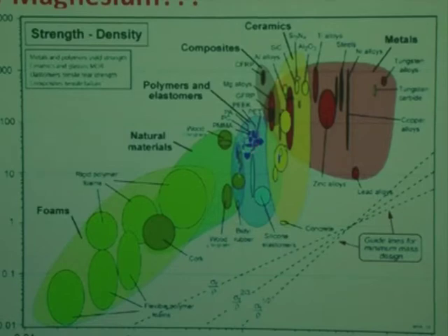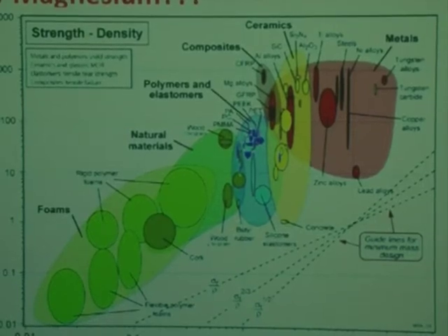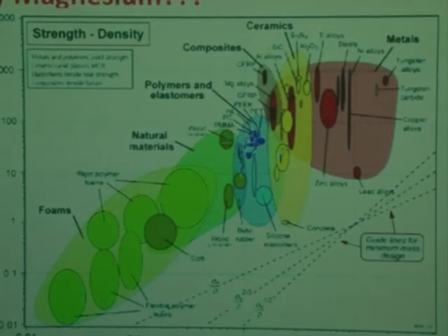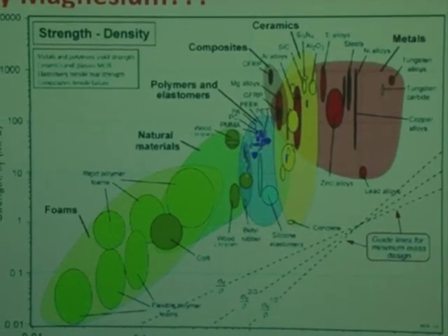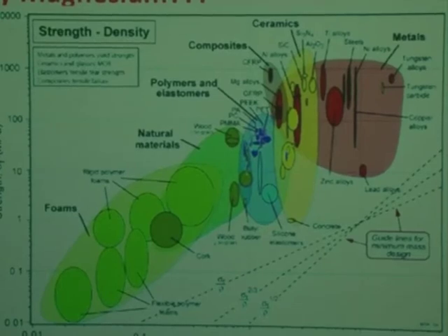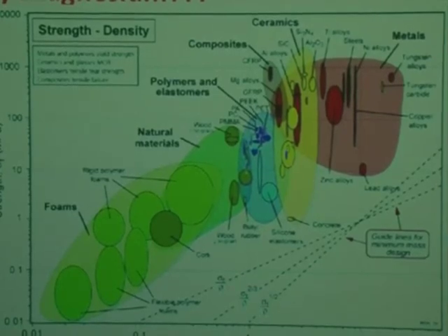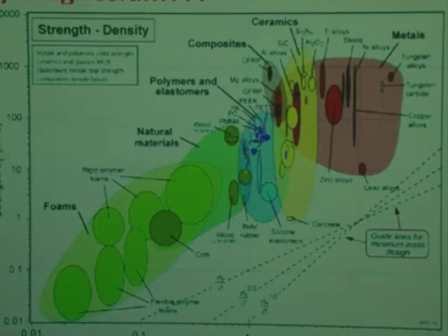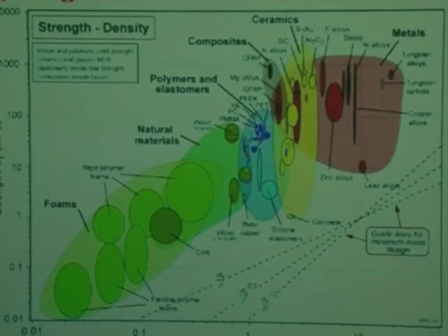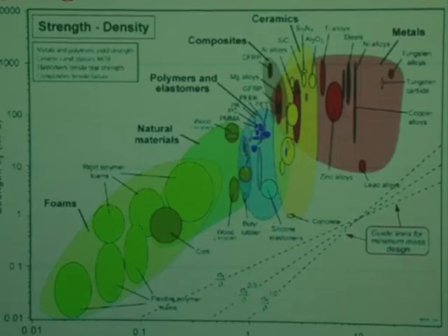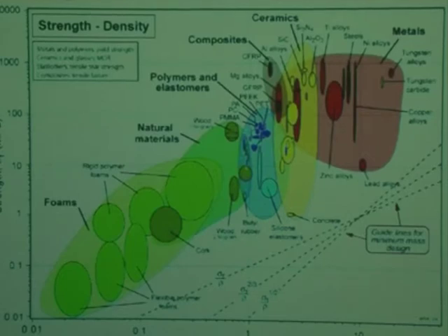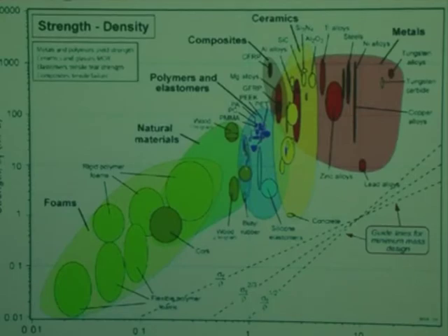It makes a lot of sense for the Chinese to go in that direction, but again, it has a lot of issues with corrosion. It's also not very stable thermally. In fact, the Chinese made fireworks from magnesium. So if this vehicle ever catches fire, most likely not only the fuel will burn, but the car itself, the chassis, will be on fire. But I say, there's a huge investment right now in magnesium. In fact, you'll be seeing magnesium in many, many applications. Compared with steel, which used to be the thing in materials, at about 7.8, magnesium is about 6 times lighter. So that plate that you have is about 6 times lighter than steel, which is fantastic.